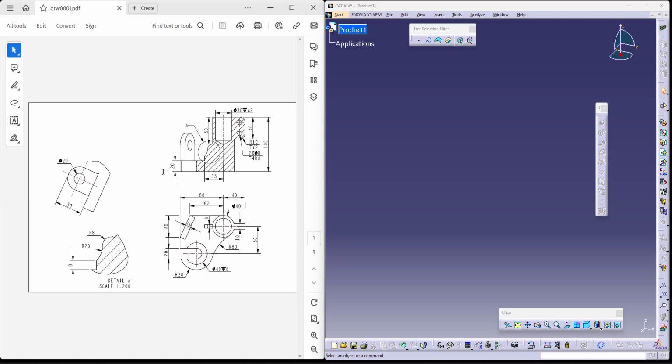In this video, we can see that there are four views shown to us. Firstly, we have to understand that this is a first angle projection. After that, we can also see that there is a front view, there is a top view, and there is another view which is an auxiliary view taken from this particular edge. There is a detail view given for the support over here. Now, this is basically the stiffener, as you can see, and this is the auxiliary view for this shape.